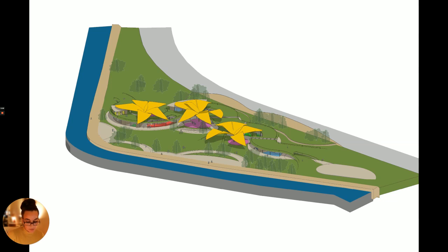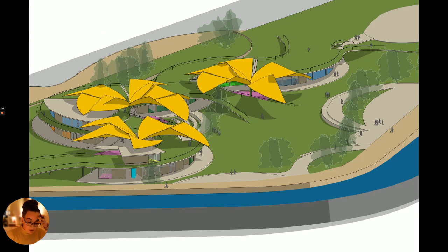The bright colors and whimsical shapes of the structures were developed in line with this project's brief specifics, which asked for a space that inspired spontaneous and undirected playfulness. I accentuated the natural sloped topography of the site with a terraced floor plan. It goes up across 4 slight level changes, 2 feet each, so it's 8 feet higher at the eastern end of the first floor. The buildings follow a curving path as they climb from the western to the eastern edge of the site.